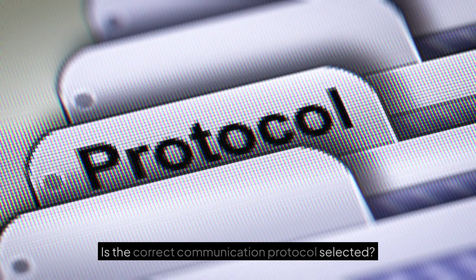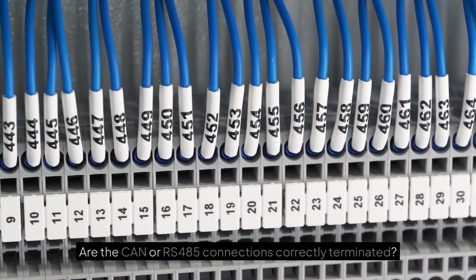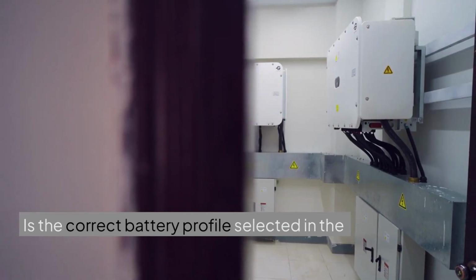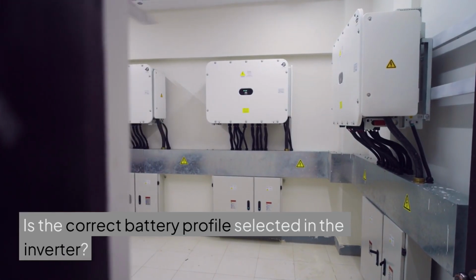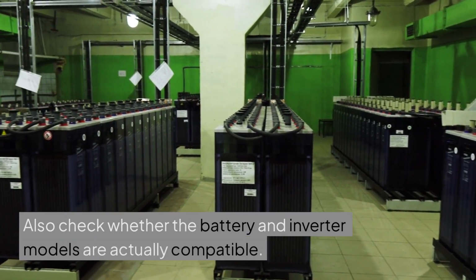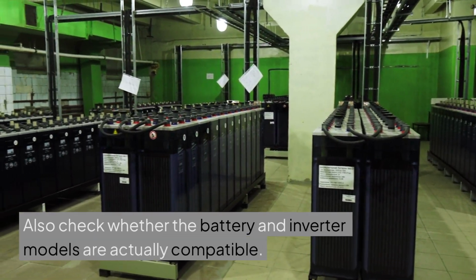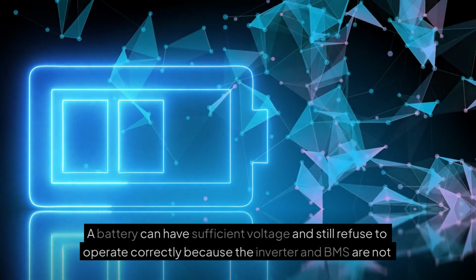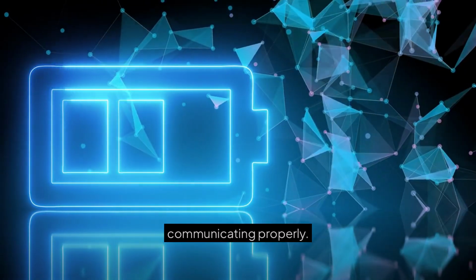Is the correct communication protocol selected? Are the CAN or 485 connections correctly terminated? Is the correct battery profile selected in the inverter? Also check whether the battery and inverter models are actually compatible. A battery can have sufficient voltage and still refuse to operate correctly because the inverter and BMS are not communicating properly.